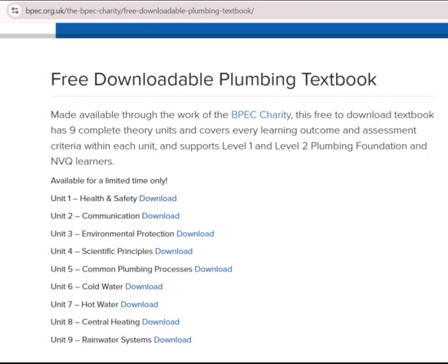The 4-pulley system. If 4 pulleys are used, the load is now supported by 4 ropes. This means that each rope is taking 25% of the load, in this case, 25 N. This means that only 25% of the weight of the load is needed to move the load upwards. The disadvantage is that a 4 m movement of effort downwards is needed to raise the load 1 m.